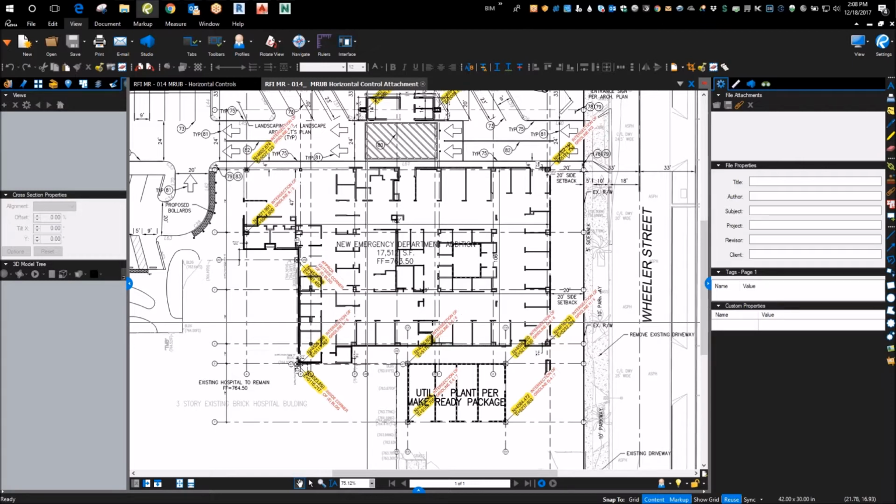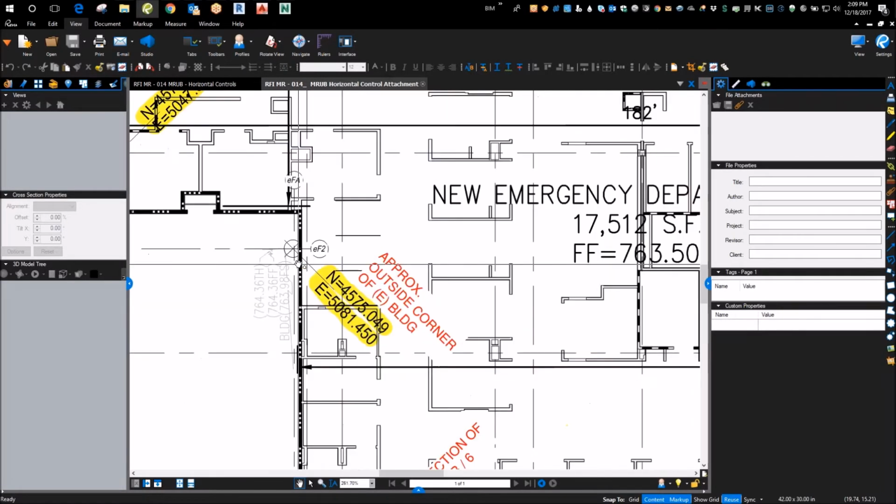Now, on a site where it's a building separate from anything else, maybe a 4-inch shift is not too big a deal. But in this case, where you're meeting it right up to the footings of another adjacent building, we only have a seismic separation. We pointed out to him that the seismic separation is specific. No go. Come out and fix it.